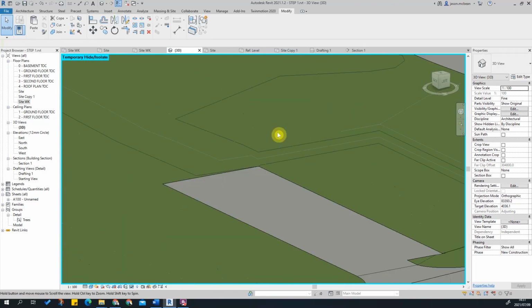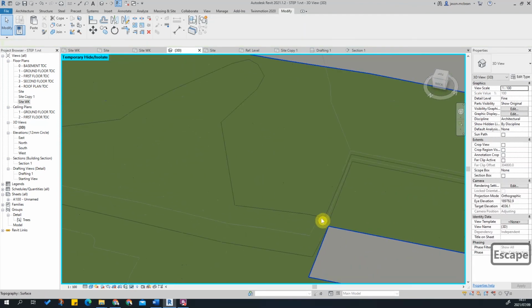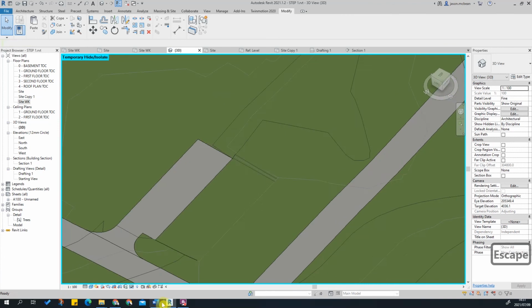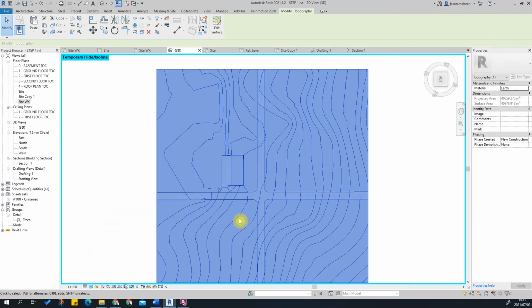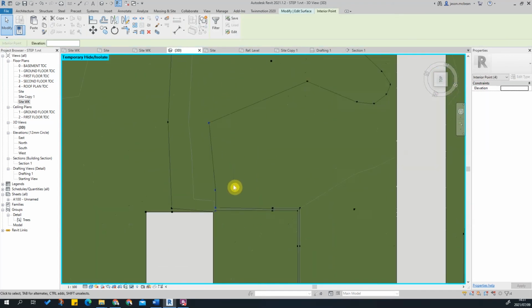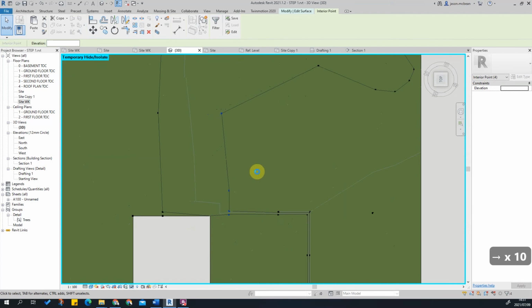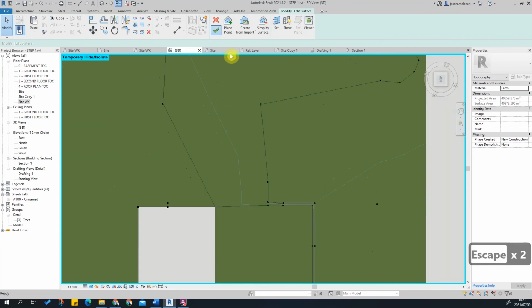Here, however, there is a slight step here somewhere, so we might have to address that. I might have to pull this meter back onto us, and let's maybe do that a bit just to increase, because you typically won't just have a big step like that. So let's just go to edit. So these points, I'm simply going to grab these points here and just nudge them back. So that's a gradual fall. Okay, that's working better. That's a bit of a plateau here. There's a plateau here. So, but that will work better. Finish command. Let's see it.